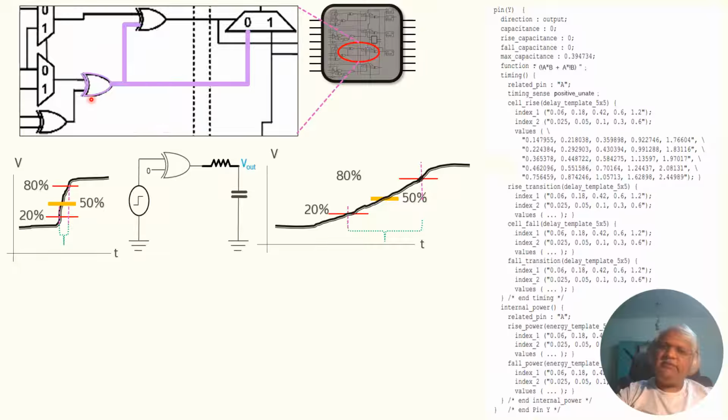Another way is to keep the VT and channel length the same and increase the drive strength of the cell, changing it to X4, X8, X16 based on the different drivabilities possible. Thus, the tool will figure out the optimal approach for so and so load.